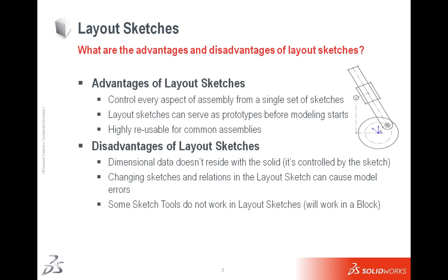Now we really need to talk about the advantages and disadvantages. I know most of you are here because you know the advantages of doing a quick layout, not worrying about all the things that we have to do in SolidWorks to put something together for a very quick layout of what an assembly might look like. Advantages of doing layout sketches in SolidWorks, for parts or assemblies: you can control every aspect of the assembly from a single set of sketches, or blocks, I should add.